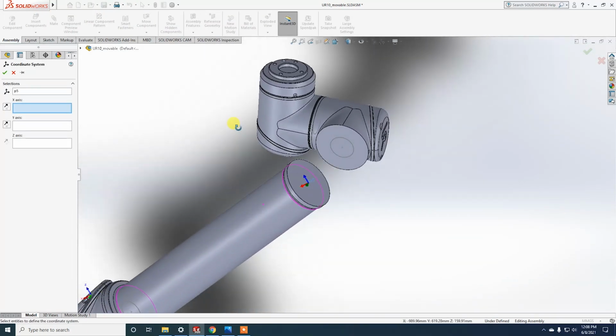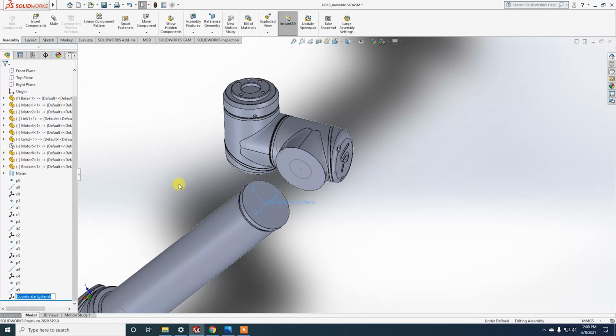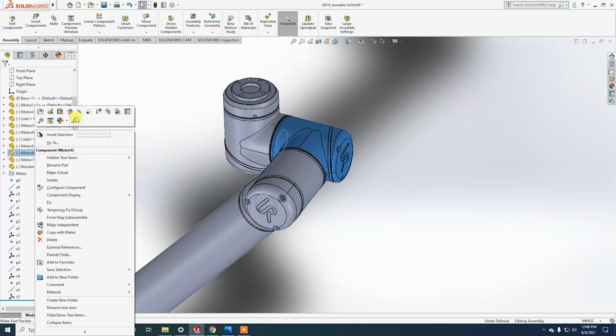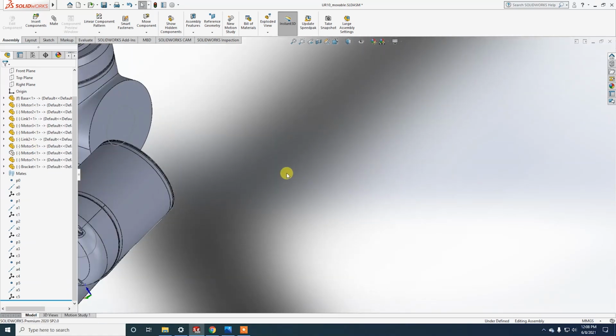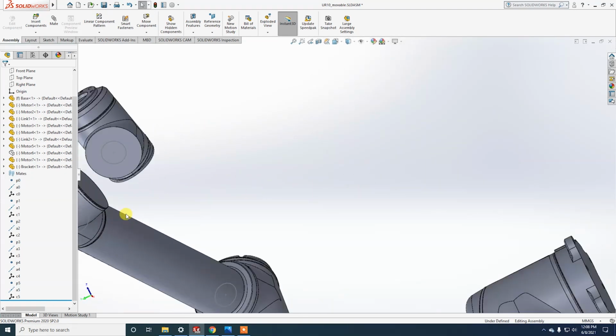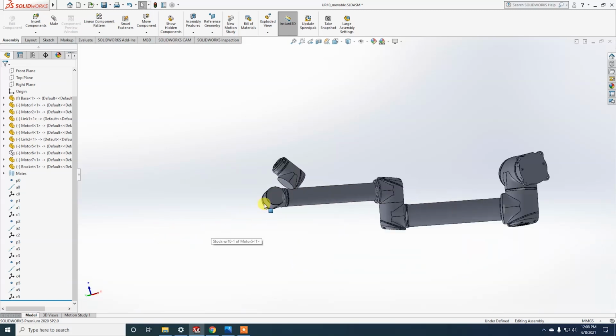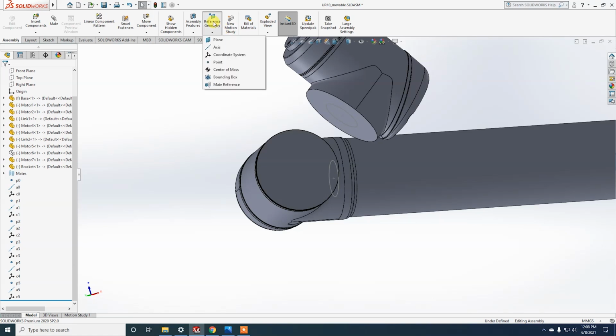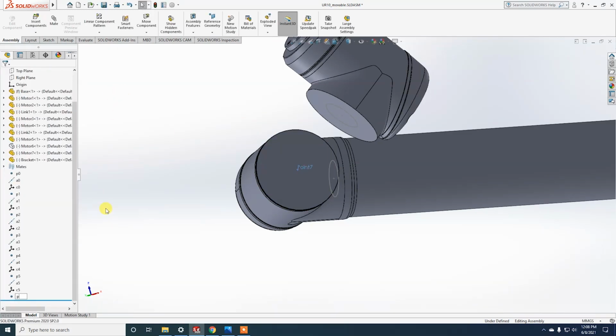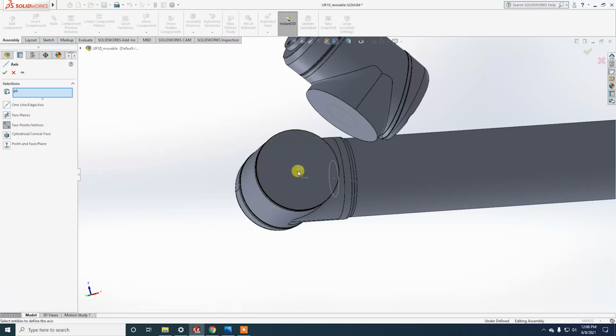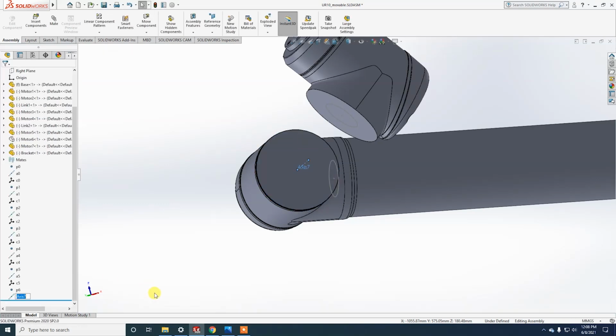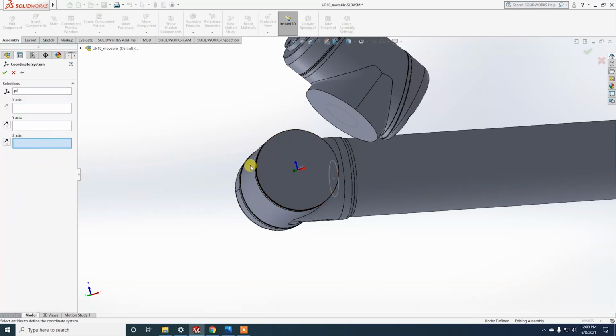Now you can see Z, the blue arrow, is not in an appropriate direction, so let's select the Z-axis and click here. Now this seems okay. Now we can see 5. Now we show this part and hide this part. So let's rotate this. Okay, so again we have to put the points here like this. Let me call this P6. Put the axis. Seems okay. A6, and select point 6 and then hit coordinates and select Z-axis and hit OK.